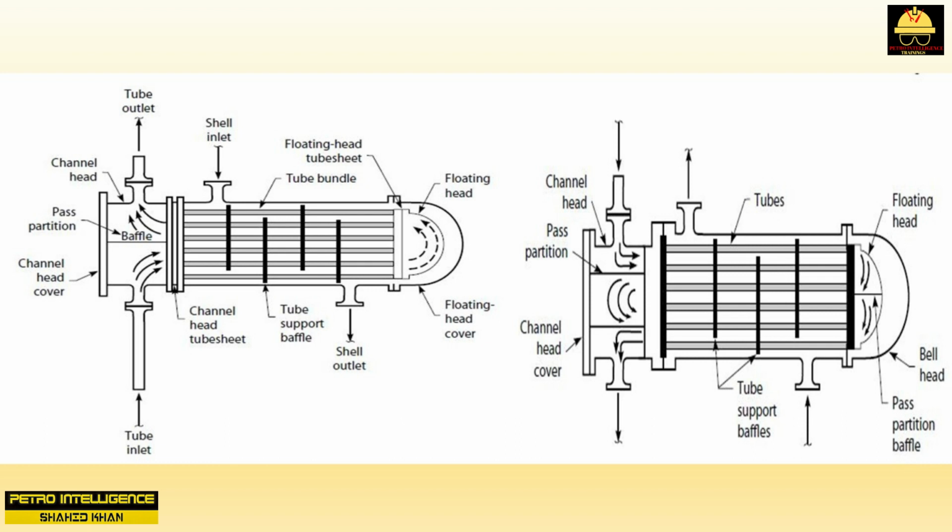The 8-fold increase in pressure drop is certainly a stiff price to pay for this improvement in the long-term U value. But remember this, it is the clean delta P of the tube bundle that will increase by a factor of 8. Let's say that the tube side of an exchanger is currently operating, after 2 years of service, in a badly fouled state. Its delta P, as measured in the field, is 20 psig. The calculated delta P for clean tubes is 5 psig in a 2-pass configuration, or 40 psig in a 4-pass configuration. After 2 years of operation, I would expect the exchanger in the 4-pass configuration to have a delta P of 50 to 60 psig, rather than 160 psig.